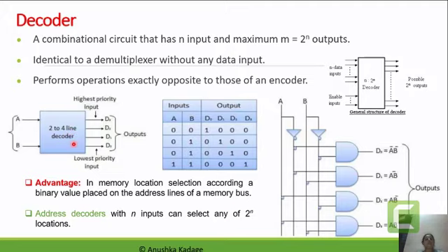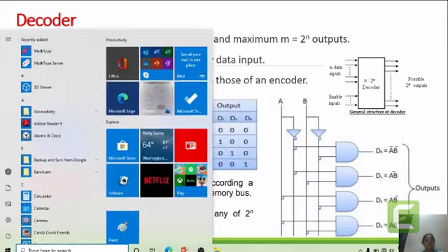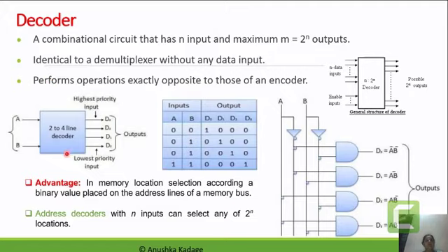That means for this decoder we will have two inputs specified as A and B, while from this decoder we will have 4 outputs, indicated from D0 to D3. Generally for the decoder operation, to decide which output we get as the decoded output, priorities will be assigned.